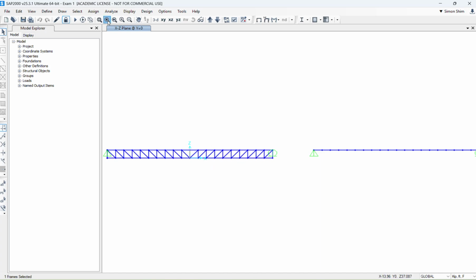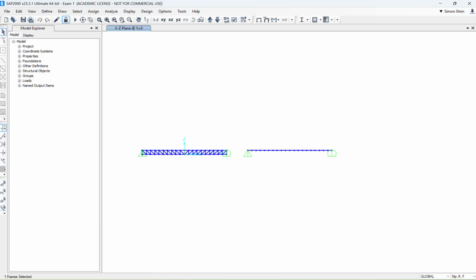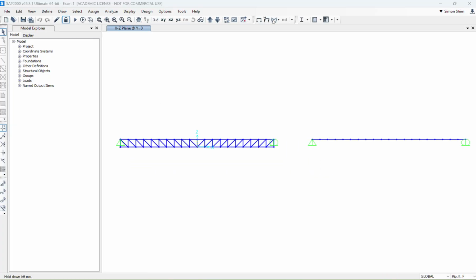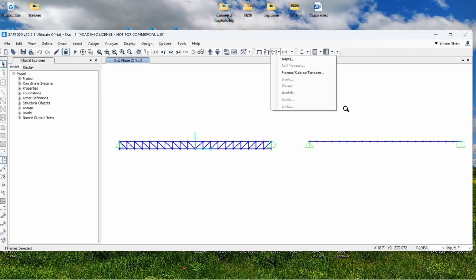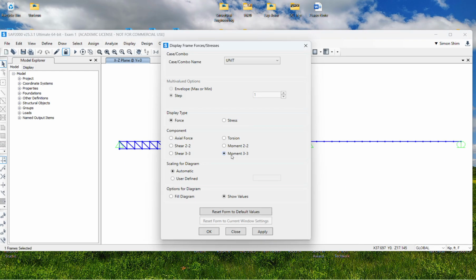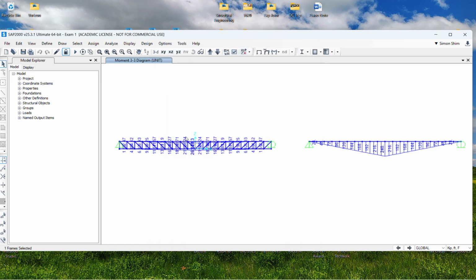Later, because there's something maybe we need to investigate a little bit. But basically, I want you to check the bending moment here on the right, by clicking unit loading bending moment 3. So it's the 20 kips times 48 feet divided by 4. You have a maximum bending moment at the middle span of 240. But in the truss, you need to look at the actual force.